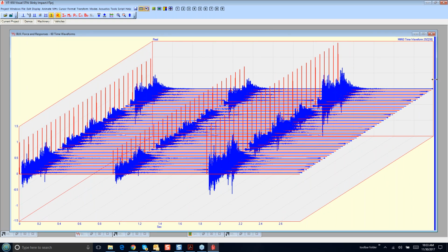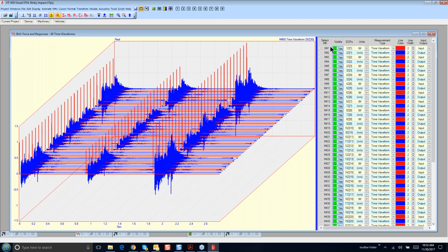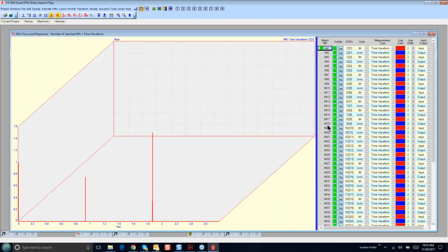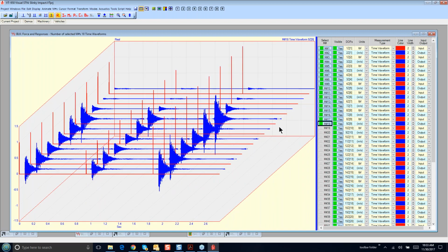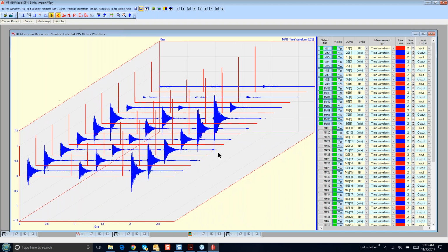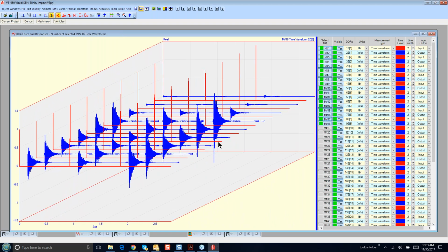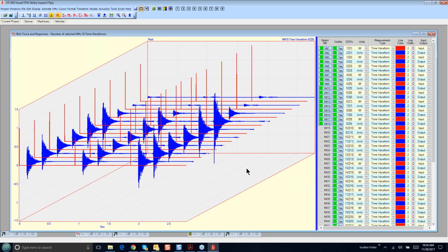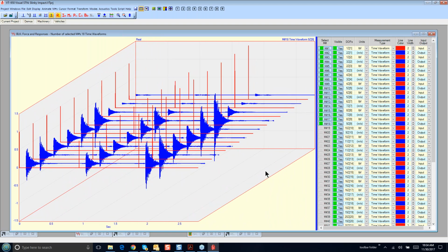So this is pairing up the inputs and the outputs, or the forces and the responses, together in a single data block, and then we're going to feed this data in and post-process it in our acquisition window and compute FRFs. Now we're going to curve fit the FRFs, then sort the residues, and we'll look at the results.